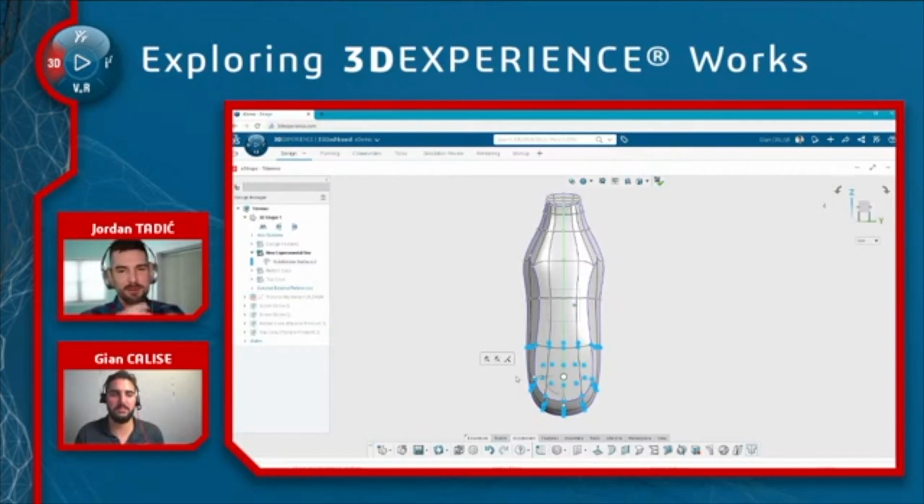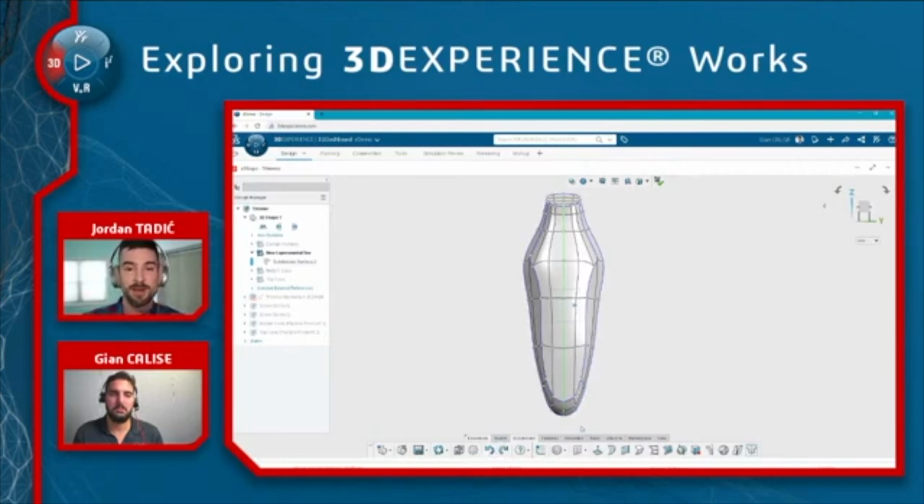But notice it's a teardrop shape. The bottom is much wider than the top. I don't know if that's what you're going for, but that's because of the successive scales. I think this would be a great place to use the flex tool. If you undo this and select all those vertices right from the get-go, and then use the flex tool, that might be even better.